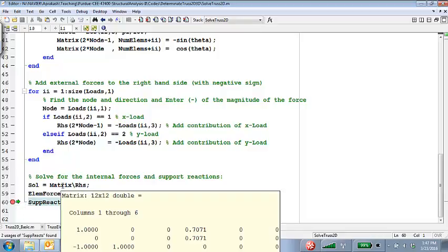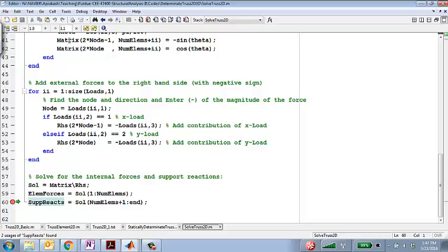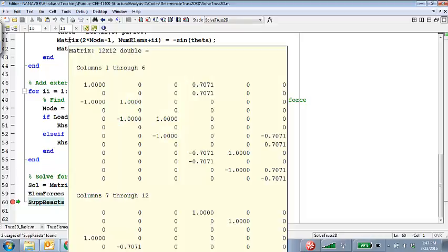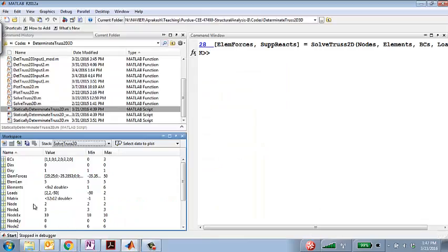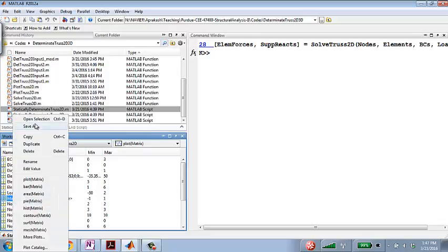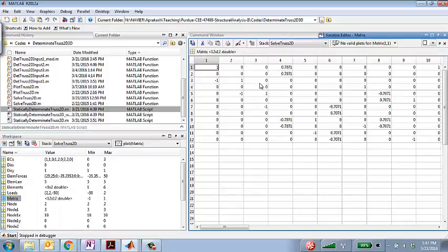You can see that the value of the A matrix has completely been calculated, which is also stored in this variable. So if I click on that and say open, then it opens up that matrix and it shows me all those values. What you can do is either open up these values, copy and paste it to a separate text file, and compare it to your handwritten derivation of the A matrix, and of course they should match.